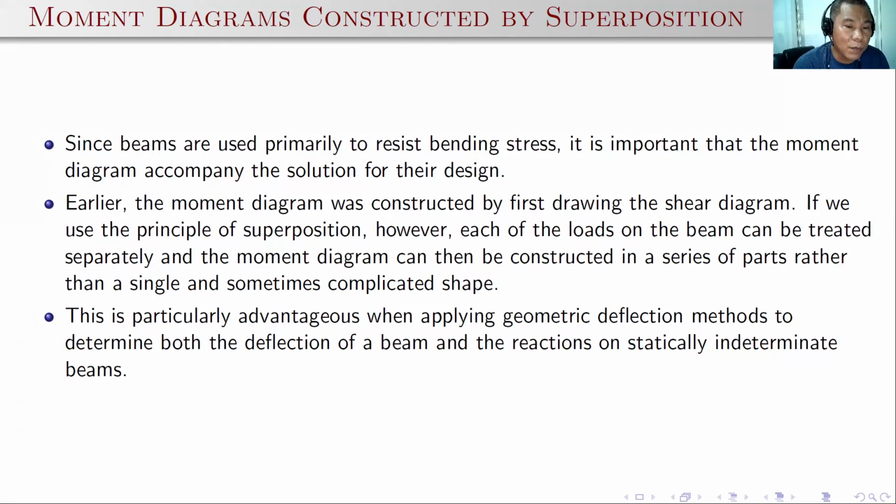If we use the principle of superposition, however, each of the loads on the beam can be treated separately, and the moment diagrams can then be constructed in a series of parts rather than a single and sometimes complicated shape. So this is the challenge actually. The examples that I have given you earlier, there are times that it seems very complicated and it would be really difficult for you.